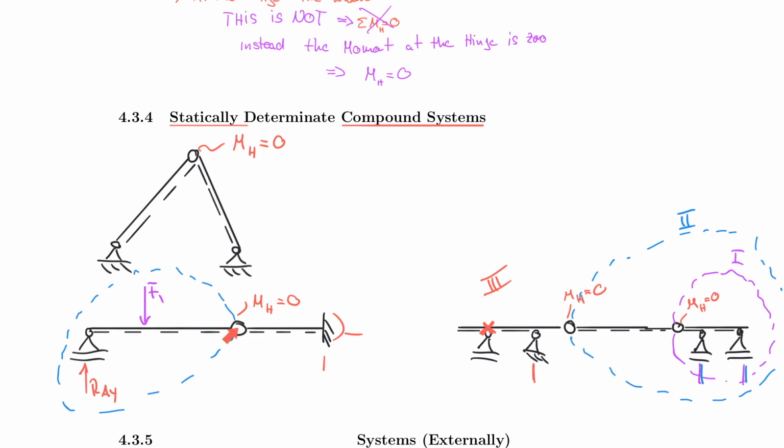And this is true because here rotation is allowed. And so this left subsystem has to be in balance. And therefore I can solve this. But then the next confusion comes in. Let's say you now already know what you have. Let's say this here would be 10 Newton, for example. Then the students often are confused. What do I do with that information? There's a hinge here. How do I calculate these remaining support reactions?